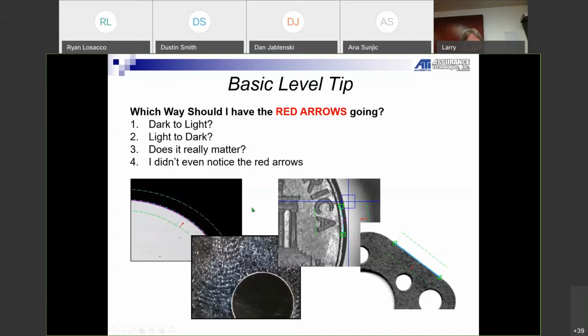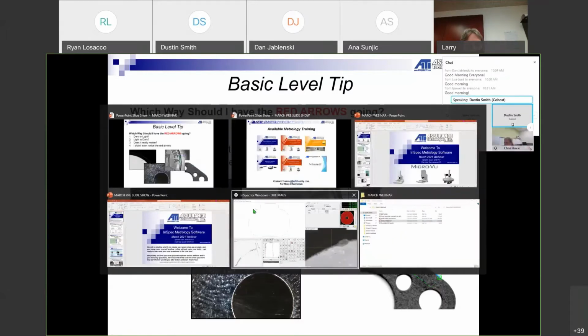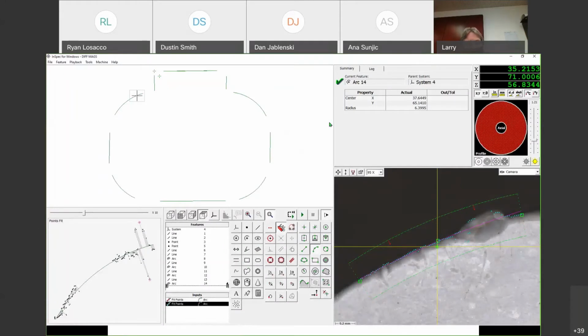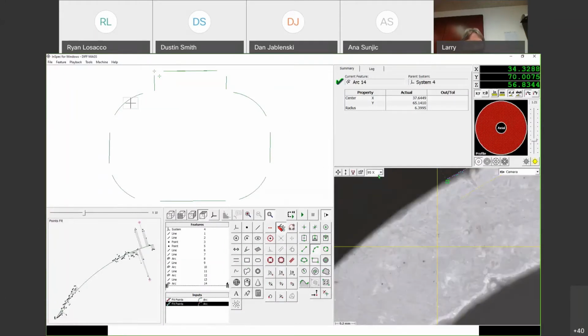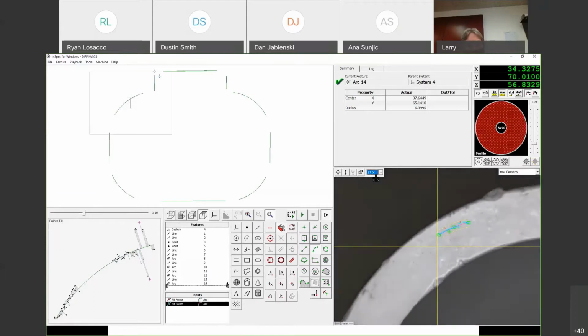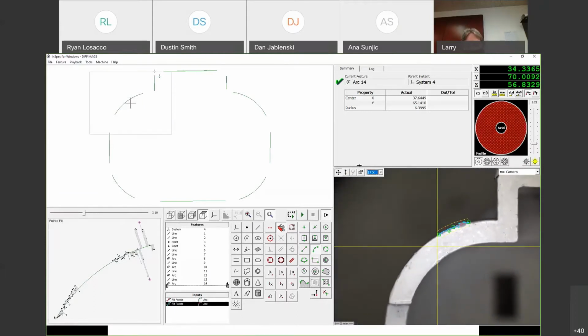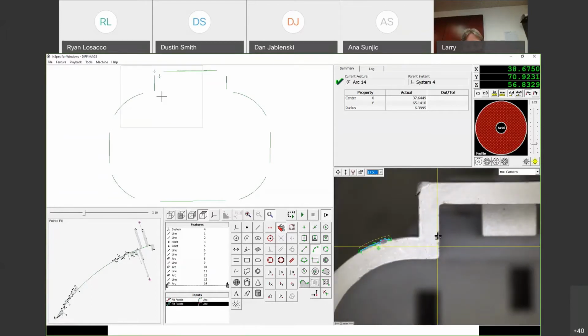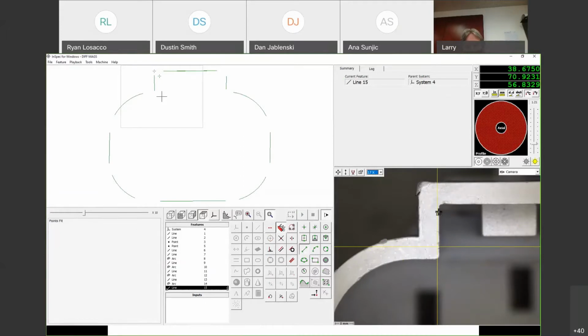So I'm going to switch over to my inspect software here. I've got this little headlight plug here. And if I came over to scan this edge right here, and I do a line and I do an F-scan line, you can see the red arrow is right here on the left. With that F-scan tool, it's looking in that dash line box for the edge close to the center of that tool. And that red arrow is the scanning direction, looking for that contrast.